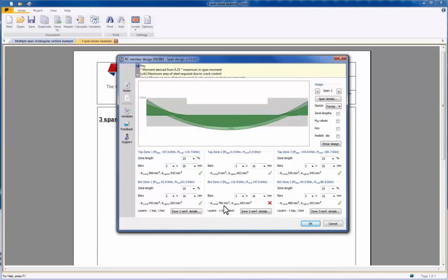So we can see at the bottom here that the green sticks out below the grey, and we also have the area error for the design reinforcement. If we tweak the bars at the bottom to increase the area provided, the grey is now larger than the green.